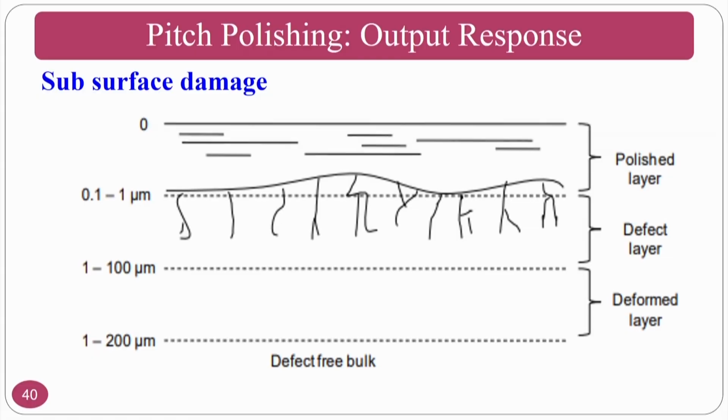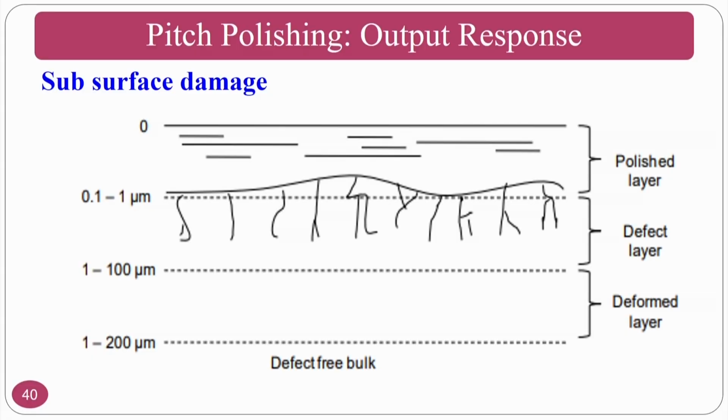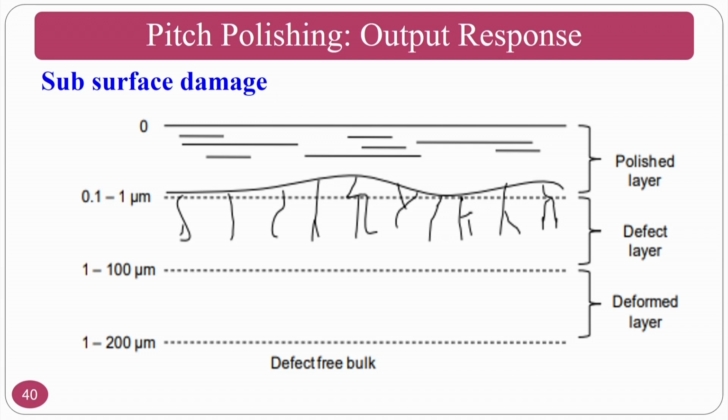Subsurface damage. If you are going for grinding applications and other things, the forces are very high. If the forces are very high, then there will be subsurface damage, cracks and other things. But in pitch polishing, this may not happen because the interaction forces are very low.